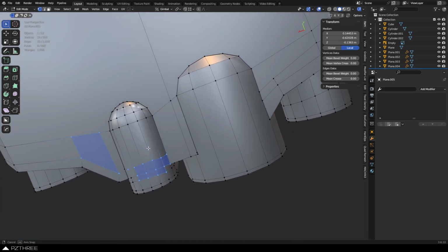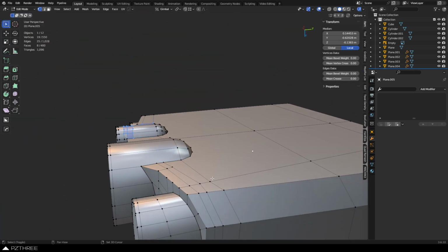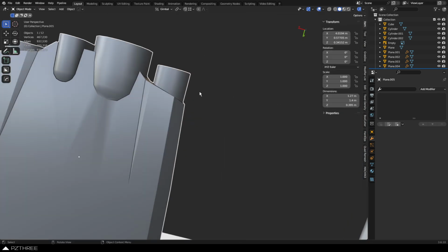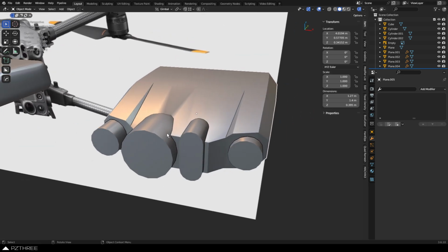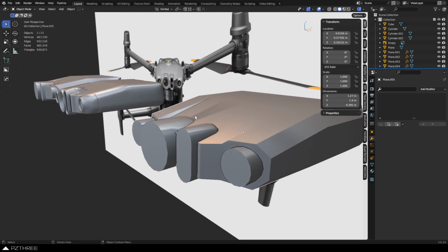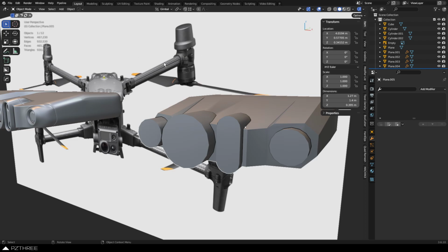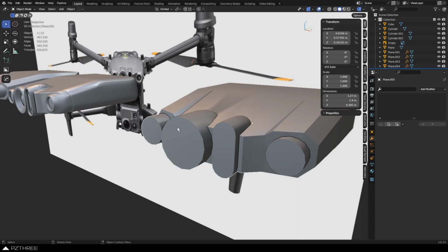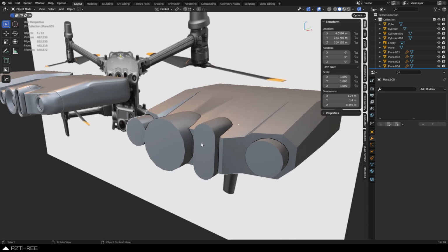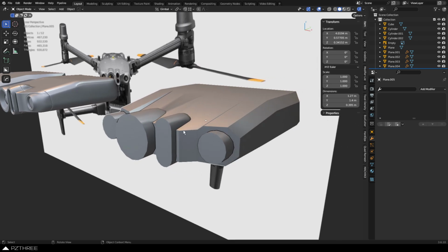So we're only focusing on this front part right now. But when you're doing a whole object, I want to point this out. You block out this front section as best as you can, right? Try to just standard model it as best as you can. It keeps subdivision in mind, but block out the whole thing because you're proportional modeling a lot of times. And if you're going to do the motors here or the blades, if those are the wrong size and this whole arm is the wrong size and the mount needs to be scaled up or something, it might influence how this body piece behaves. And then that might even influence where these line up on that body piece. So block everything out as best as you can before you even approach doing subdivision.